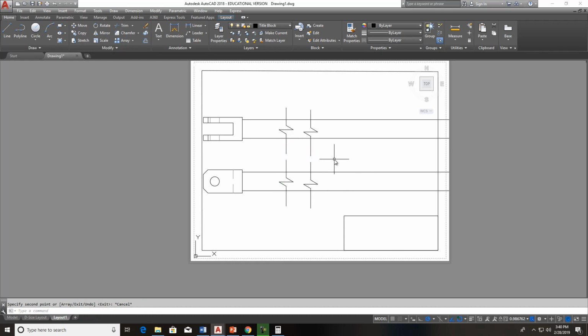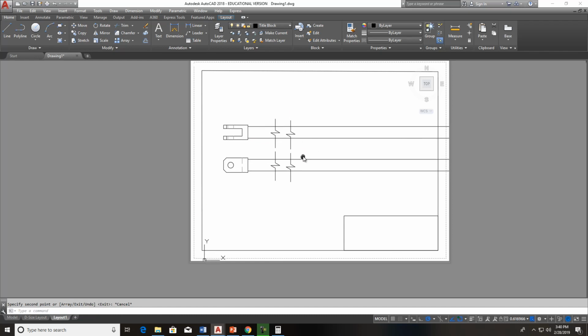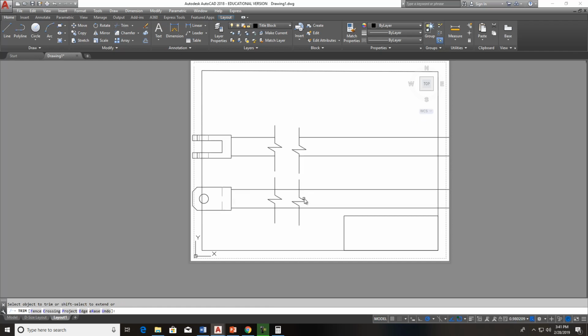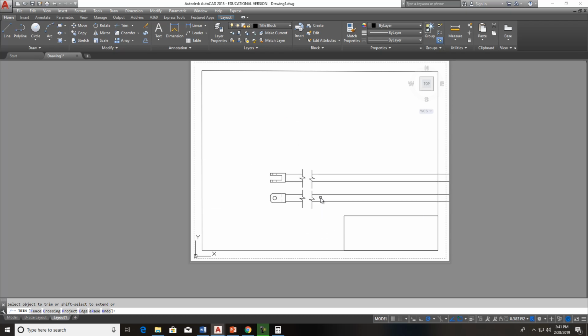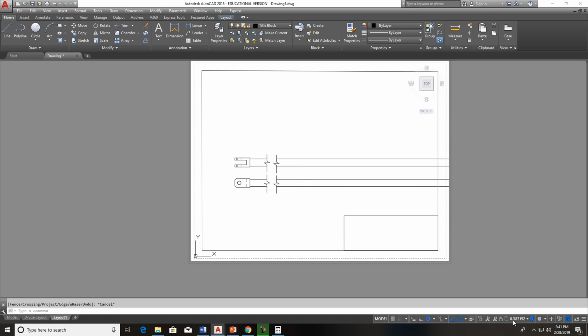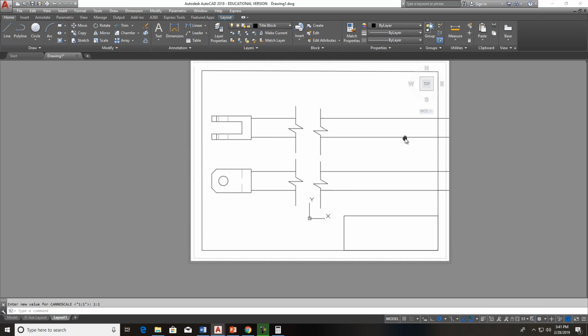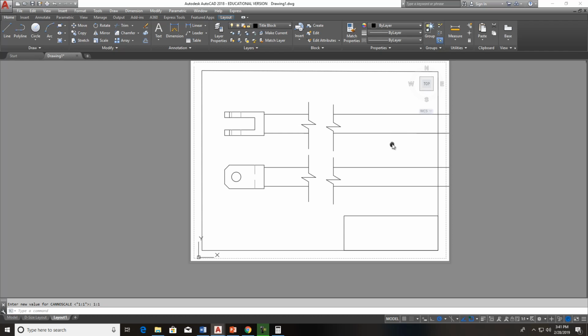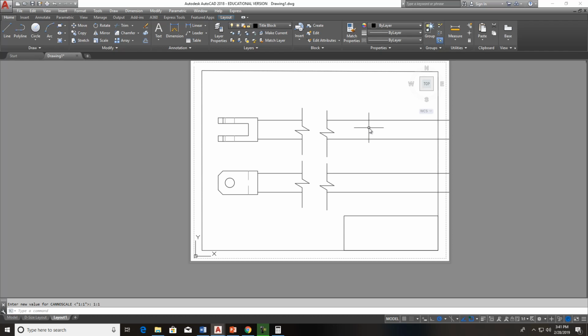Same way. And then what you're going to do at this point is just take and trim that out, trim that out, and then you can just go in here, and I'm going to go back to 1:1. And really you need a right side view on this as well, or a revolution, and we'll get into that shortly. So I'll cut it off about right here. So I'm just going to put line, just let it float nearest, and it doesn't matter where it's at. And that line can stretch on down to here, trim everything up, just like that.